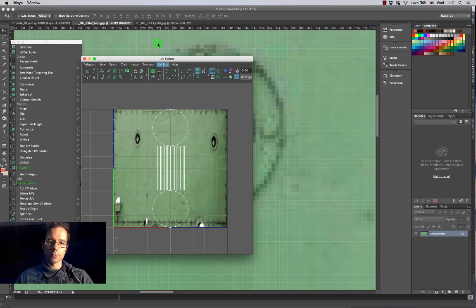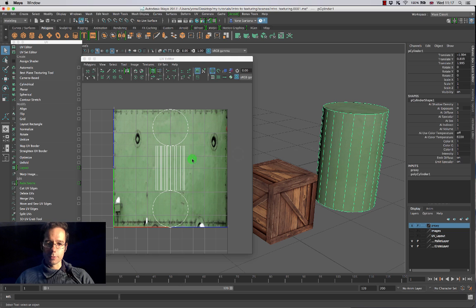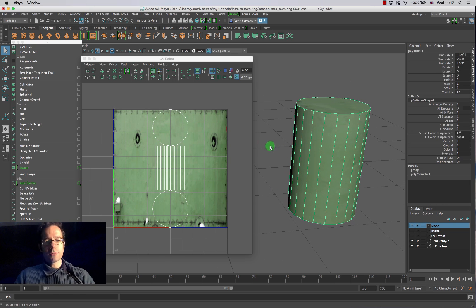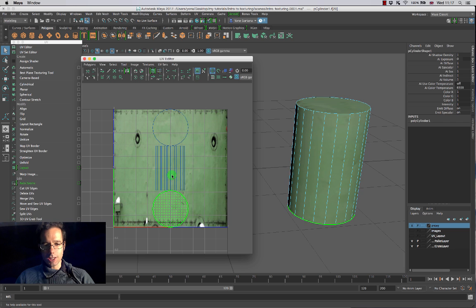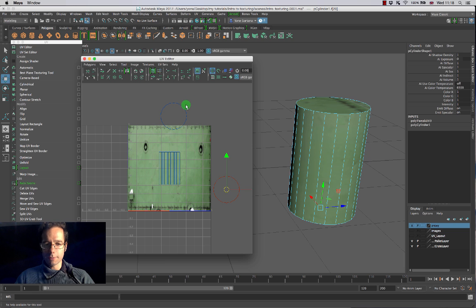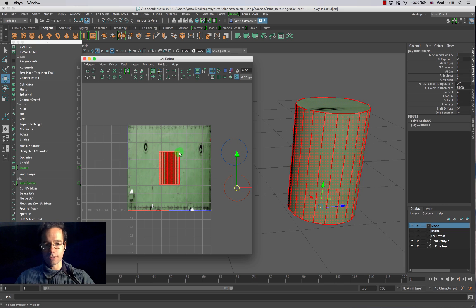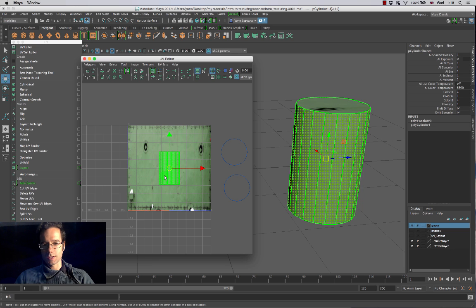But I'm going to show you some of the problems that you find when you're actually working with images inside of Maya, just like this. So when I'm unwrapping my UVs over here, I have to go back to the UV editor. And again, remember that if I choose shell, Maya has already taken out these shells over here, and you're going to see that I can select the top shell over here and move it out, and I can take this bottom shell over here and move it out as well. Never feel worried about moving UV shells out of this space. We're going to move them back later on. But importantly, sometimes I just like getting things out of the way over here because I'm going to do some manipulations to this thing over here.